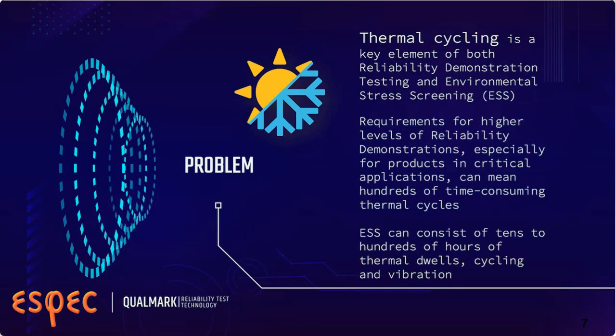It's the cornerstone of much of the traditional reliability demonstration testing that is done, as well as environmental stress screening done during production. There is a key problem with thermal cycling, however. It can take a long time, especially when your products are extremely high reliability products, and you're trying to demonstrate that you meet those high levels of reliability. It can take hundreds of thermal cycles and hundreds of hours to meet those testing requirements. And this can be a serious problem when your timeline is short, when you're trying to get things out the door.